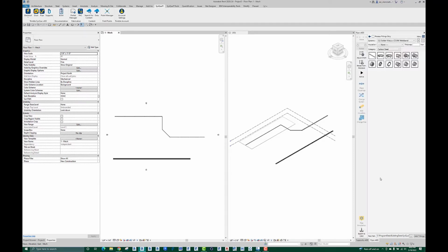So let's go back and say we're going to look initially at just placing manual hangers. This is a type of scenario where I only need 2 or 3 hangers, maybe a hanger around a piece of equipment. Maybe I've got a complex beam system, so I do need to physically make sure that each of the hangers ends up on a beam. Another reason to manually place them rather than automatically place them.